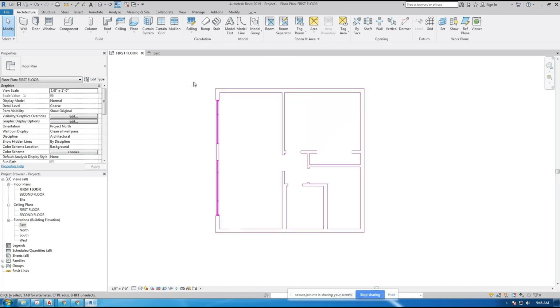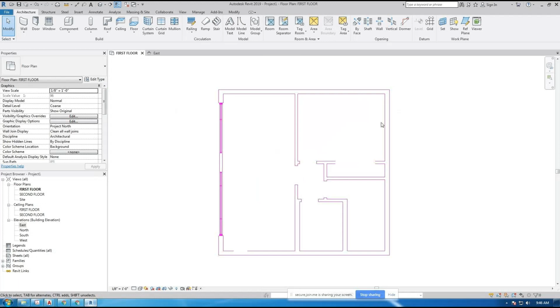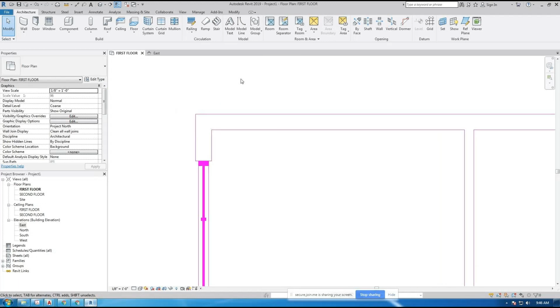All right, so let's understand this file. How thick are these walls? I want to make these exterior walls, and let's figure out how thick they are. So if I zoom in, Revit has a little shortcut, a little tape measure, right here at the upper left, looks like a little piece of tape next to the printer. If I click on that, and I have Revit snap to this line. Now, you want to look for a snap, which is like a little magnet that gets stuck to a line. You want to measure how far it is between this line and this line with a straight line.